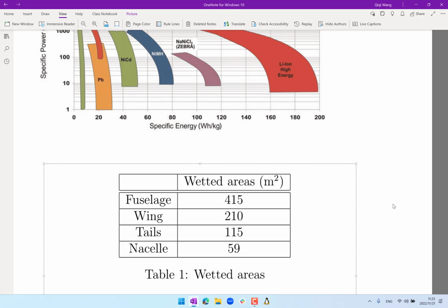So you don't really want the airplane behind to fly in the downwash of the towing airplane. Presumably the towing airplane is loaded full of batteries and has a lot of weight, so as it flies by, it has to push the air down. If you're flying in the wake that's being pushed down, you are artificially tilting your lift vector even more backwards, because you are seeing a free stream that is already going down instead of horizontal.